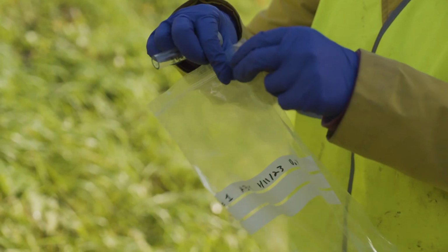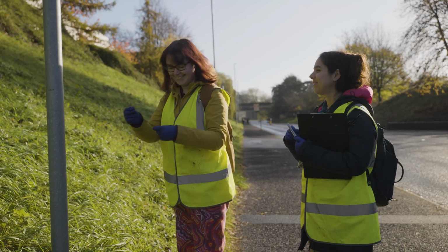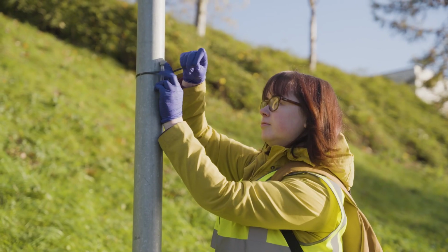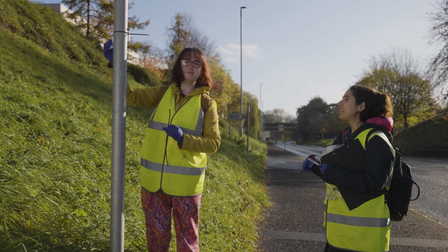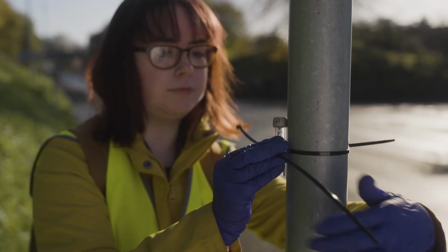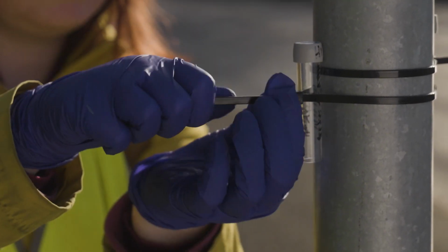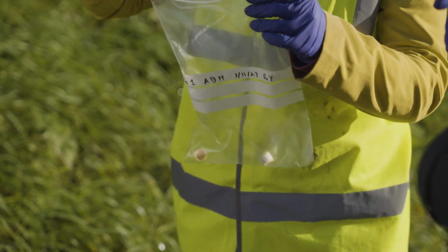To use diffusion tubes, remove them from refrigerator storage and transport them vertically in sealable plastic bags. Once at the sampling site, these should be labelled and mounted securely to a fixed object. The absorbent closed cap should be positioned at the top, with the other cap removed, leaving an open end for air to passively move into the tube. Make sure you retain the cap in the labelled sampling bags to reuse when the sample is collected.